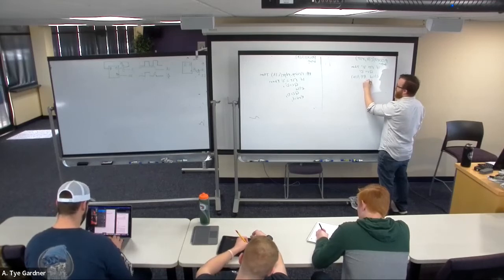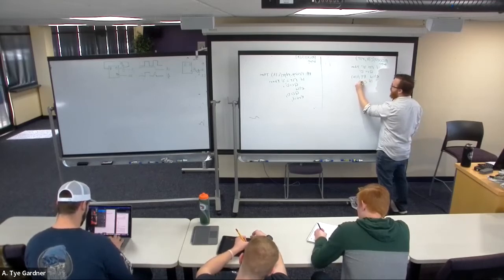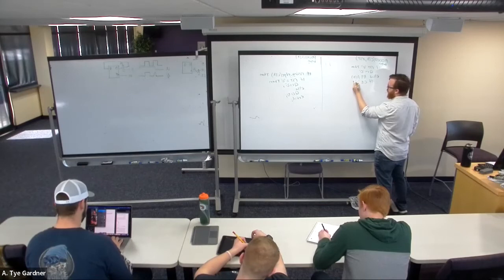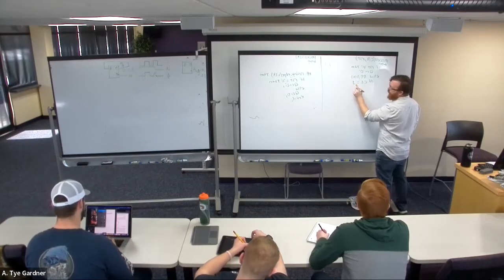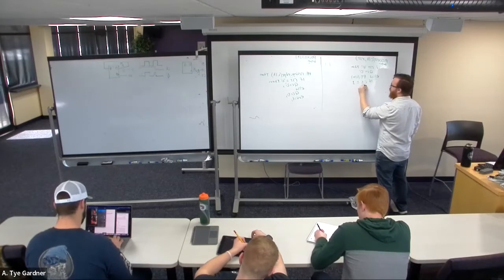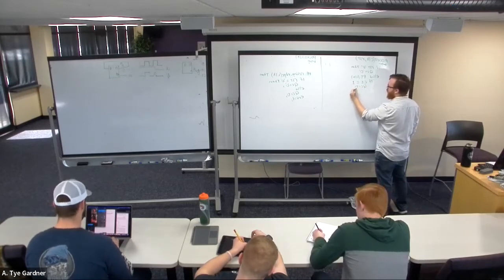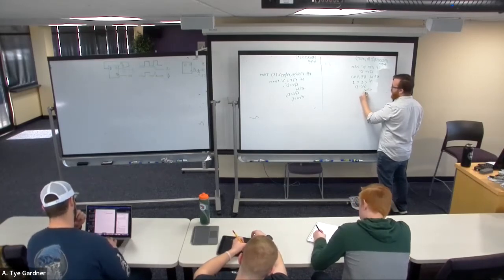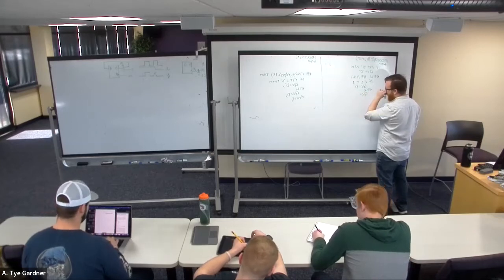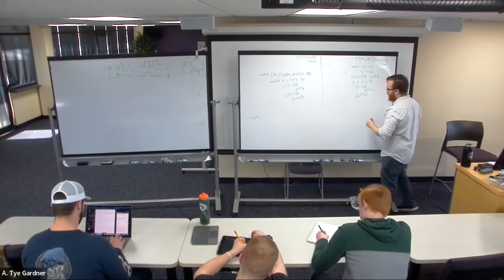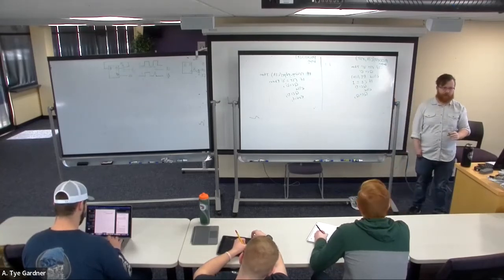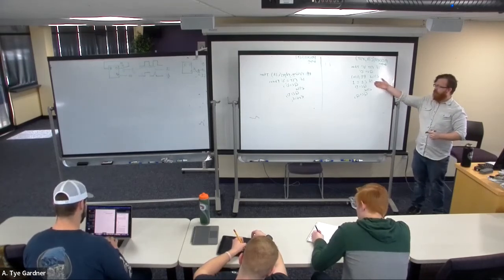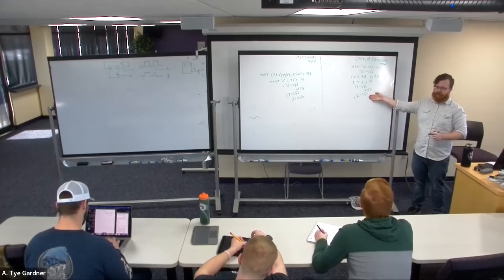and then I just have to say if CE equals 1, equals, not assigned to, if CE is 1, which is going to take the new D, else Q gets assigned to Q. If CE is 1, get the new data, otherwise stay the same thing.